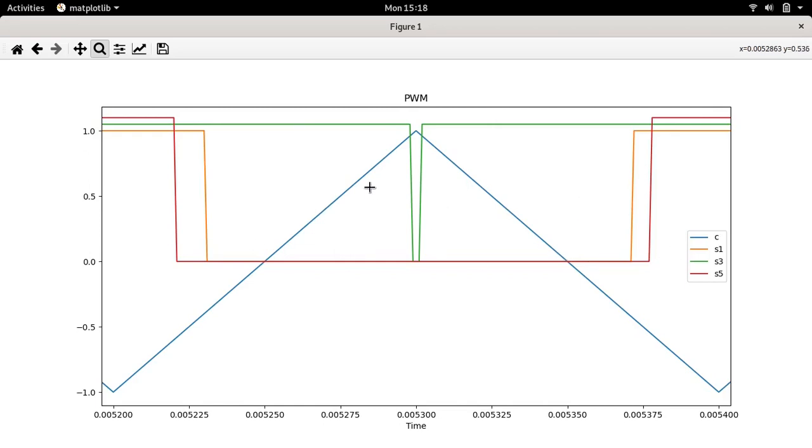That's a good thing because we want to apply a certain voltage. That is, we want to apply a certain voltage in the A phase, in the B phase and the C phase. And the objective of this is to produce certain currents or to produce a certain 3-phase output voltage, right? And we want the average value of our 3-phase output voltage to be a certain value over the entire cycle. So if I were to calculate the average of this 3-phase output voltage, we can do this for the A phase, the B phase and the C phase separately.